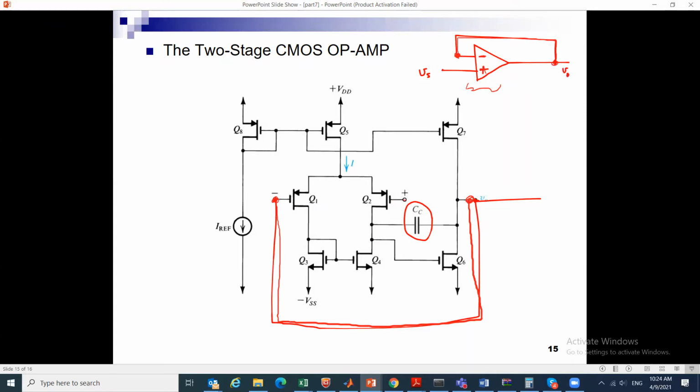And this is a non-inverting amplifier, right? And 1 plus R2 over R1, right? And we explained that the feedback beta comprises 1 plus R2 over R1. Here R2 is 0 and R1 is infinity. The circuit is not like this, right? And this is a unity, a voltage follower.